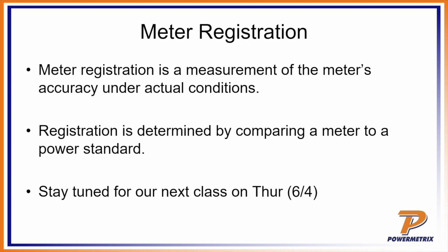So the meter registration is just a measurement of the meter's accuracy under actual conditions. We talk about that all the time. We test for it all the time. That's what we test, either in the shop or in the field. We're going to compare the meter to a standard, and we're going to talk about that a lot more on Thursday. Okay, but I just wanted to let you know.